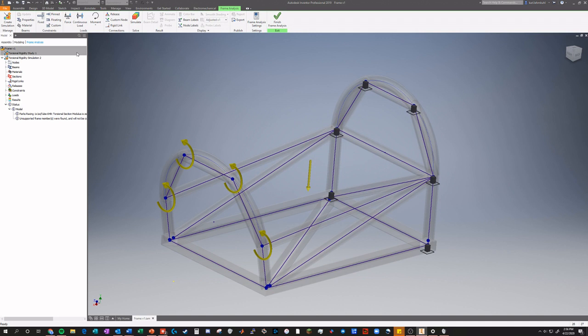So it's more important that you spend your time as the simulation guy trying to get as much simulation data as you can, and trying a couple different geometry configurations, or maybe tube wall thickness configurations, than it is that you need the exact weight value down to a tenth.